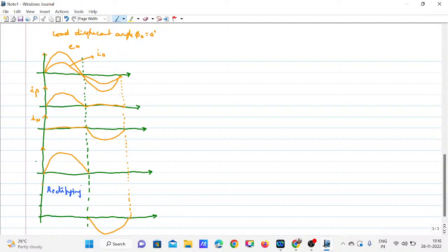Okay, what exactly happens in our rectifier? The same operation happened from the positive half cycle, you can see here, and this is for the positive group. So in the positive group it is simply having rectifying action from 0 to pi. After that what will happen? After that there is no conduction in it, so it becomes idle after this.